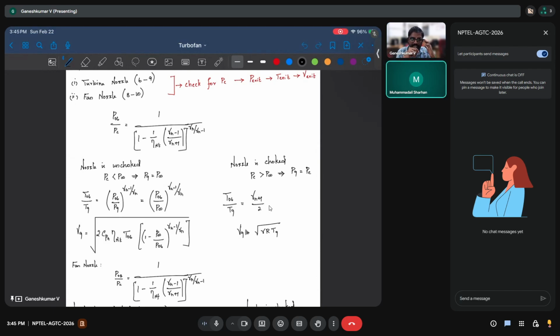It doesn't mean that efficiency is not there. In fact, if you look at it, the critical pressure ratio that you found depends on efficiency, right? So the critical pressure already depends on efficiency, and since the velocity is equal to the speed of sound, it doesn't really matter. You need not include efficiency in it, because it is an inherent property of the gas. Okay, thank you, sir.